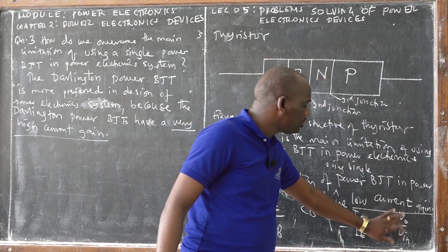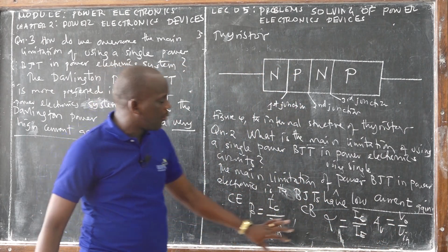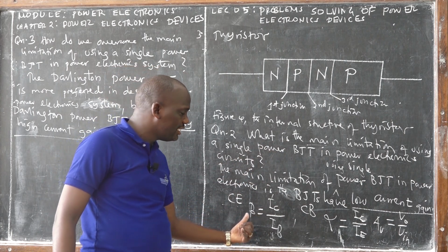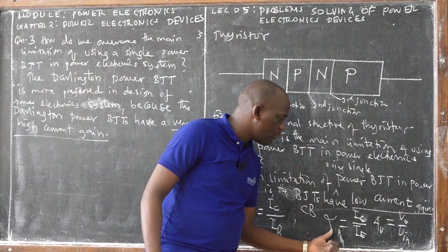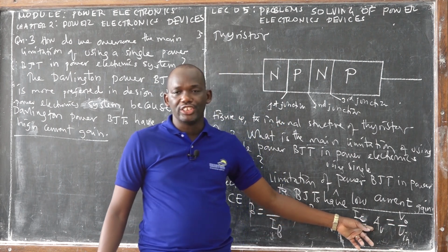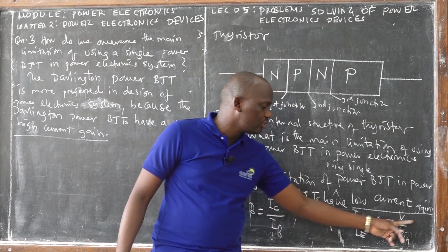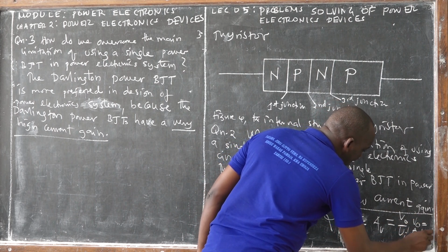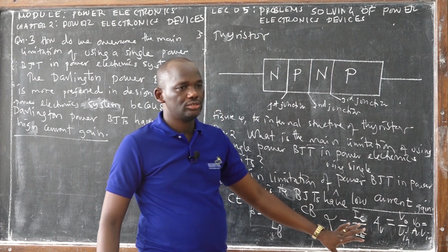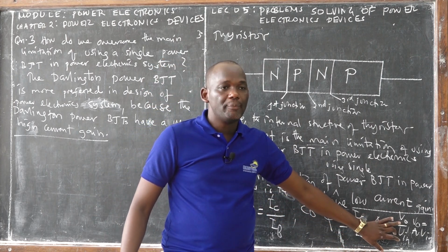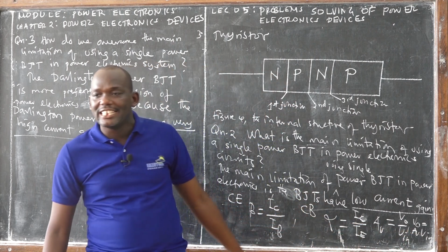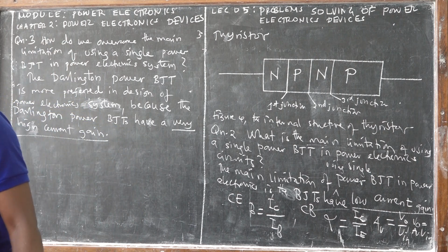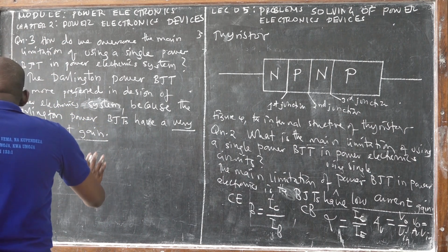When you keep deriving this formula based on the circuit, you'll find the factor of current gain in common emitter or common base is a part of the voltage gain. If you want a high output voltage, it is equal to voltage gain times input voltage. So this voltage gain depends on the current gain. The higher the current gain, the higher the voltage gain. Are we together?